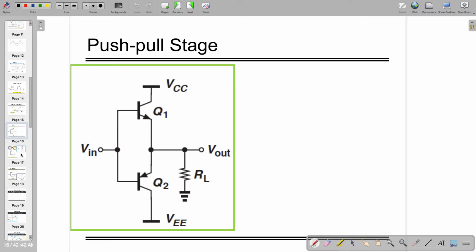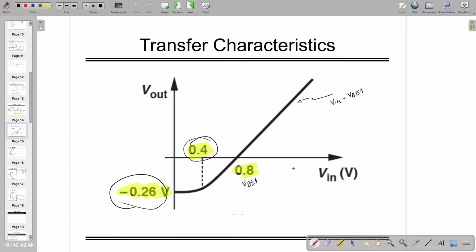and they add the advantages of both. So what exactly happens is, instead of this characteristic, if you have this kind of circuit, this is also common collector, and in this case you can also have minus. So the characteristic will not be like that, but will look like this one. This is Vin versus Vout, where this is equal to Vin plus mod of VBE. Let's call it VBE1,